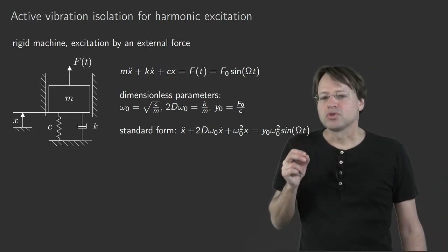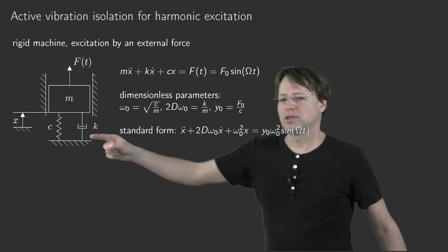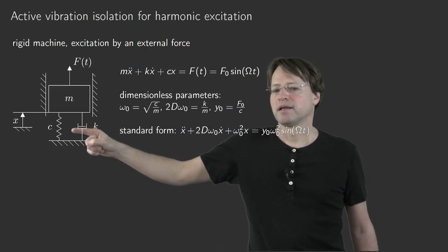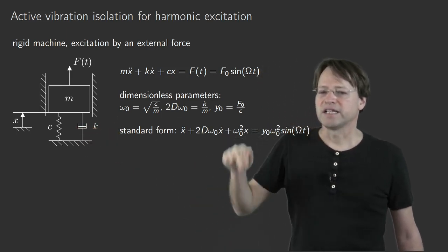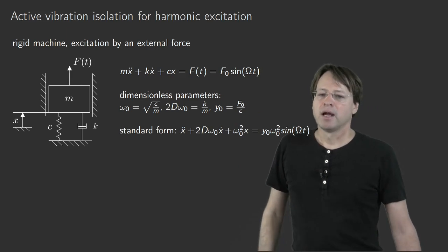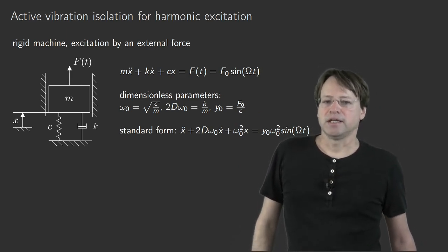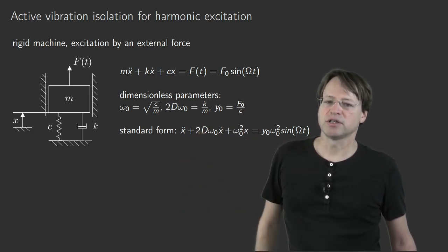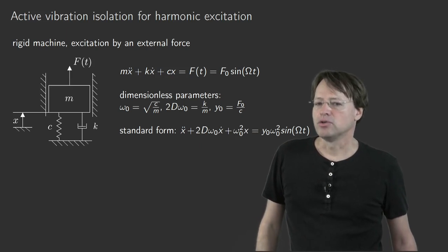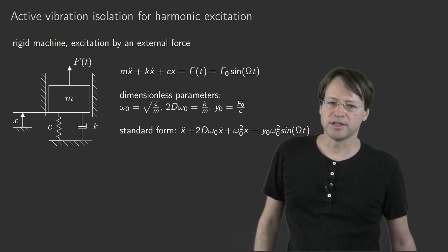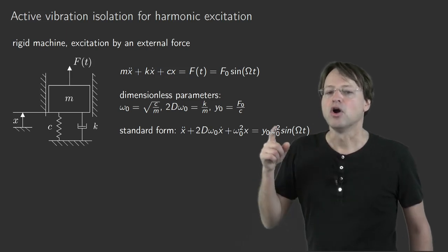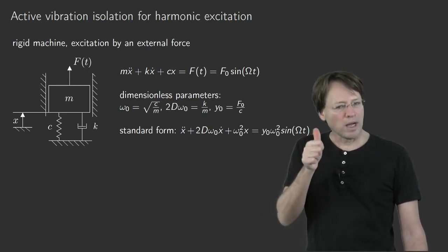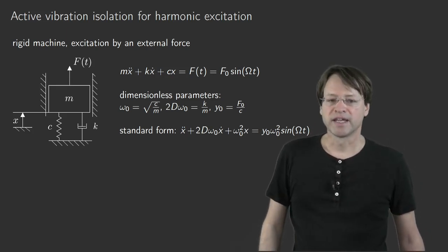I would like now to solve that equation in order to compute the displacement x, and then the force, spring force and damping force that acts on the foundation. Well, as you learned in engineering mechanics, when you consider such an ordinary differential equation, the solution is given by the general solution of the homogeneous equation, which is obtained by setting the right-hand side to 0, and one particular solution.